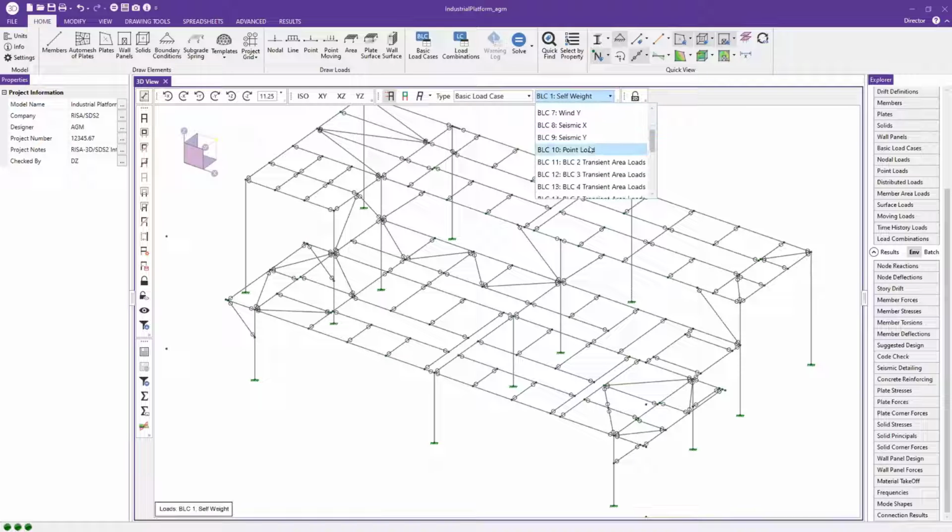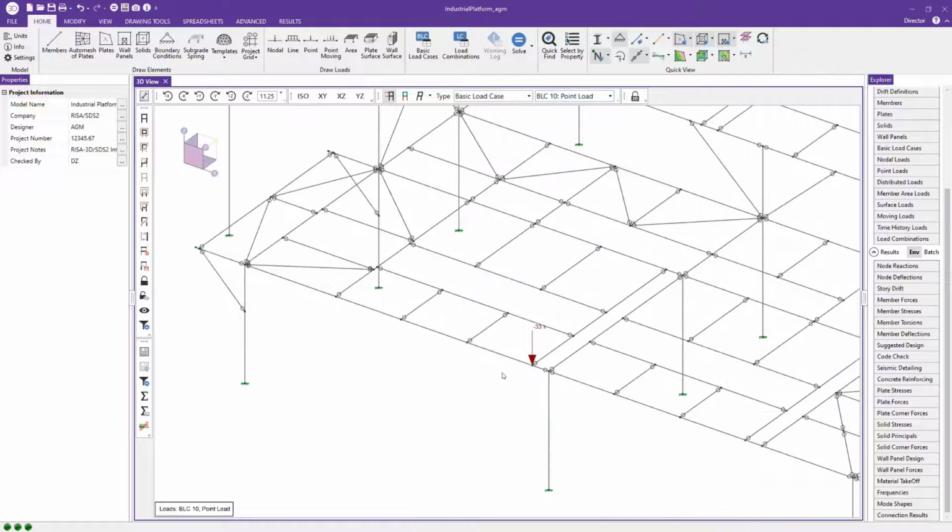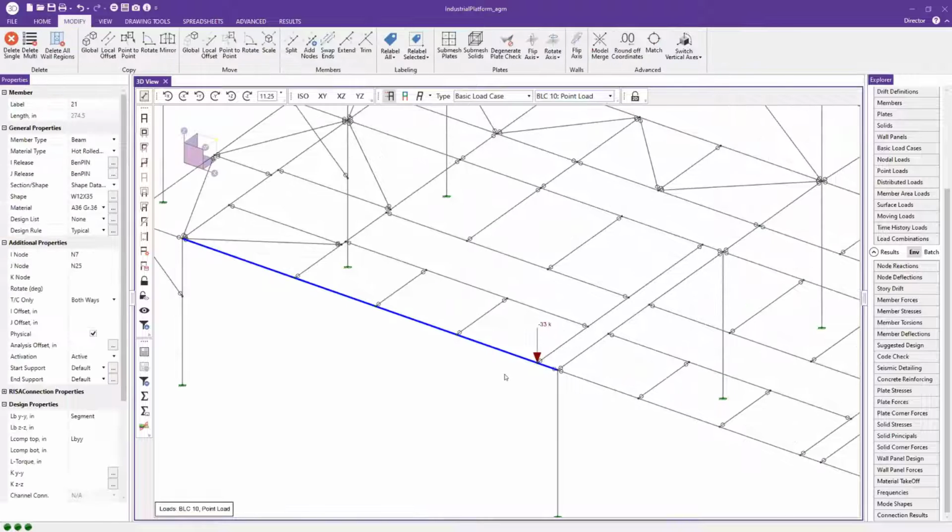is a situation like this, where say I have a very heavy point load right on the end of a beam, something like this. A really heavy point load. This beam is fine, it's well within its code check value, but this point load might create an end reaction here that is actually greater than what I would get if I were just using the uniform or the ultimate distributed load method.